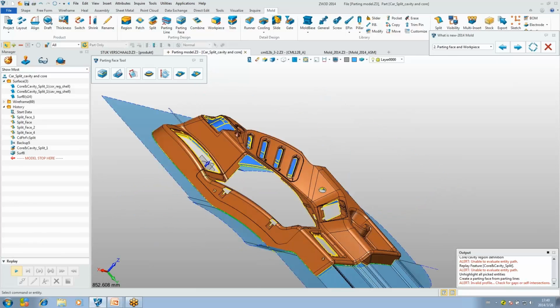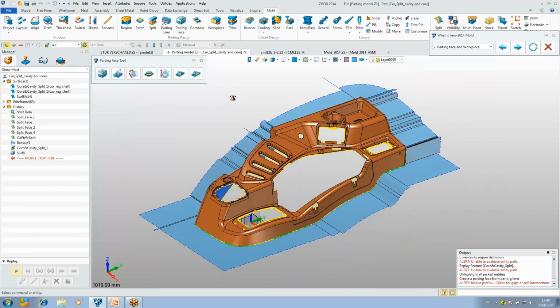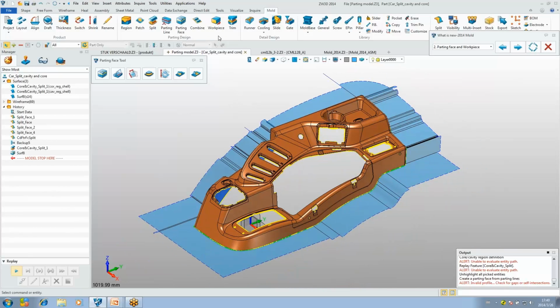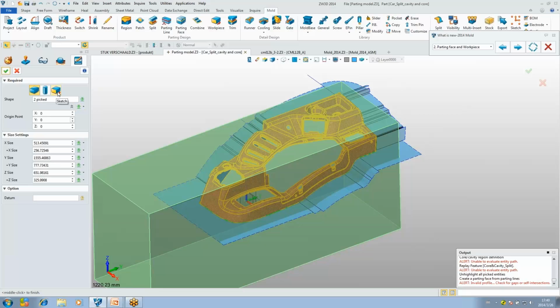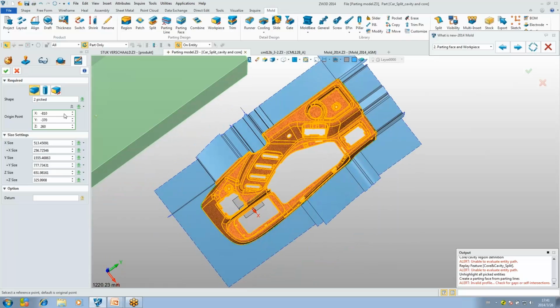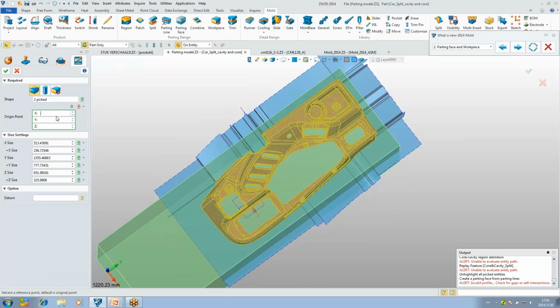Another new improvement is the workpiece, like what I said just now in the PowerPoint. Let's click the workpiece. You can see that it's set to the extrude from sketch function. ZW3D supports using a block and cylinder to create a stock size, so that you don't need to create a 2D sketch first. Here let us define the origin point. If you don't set the origin point, it will use the yellow point as the origin.